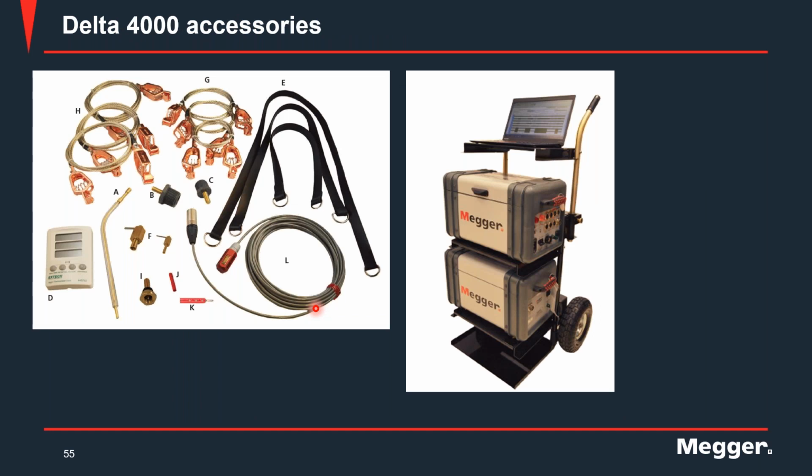There are accessories available with the power factor test set. I'm not going to talk a whole lot about it. I'll just briefly go over some of these. The accessories include some shorting cables for shorting the bushings. You have different bushing adapters which allow you to make a solid connection on the test tap. And then there are semi-conductive straps which can be used for hot collar tests.